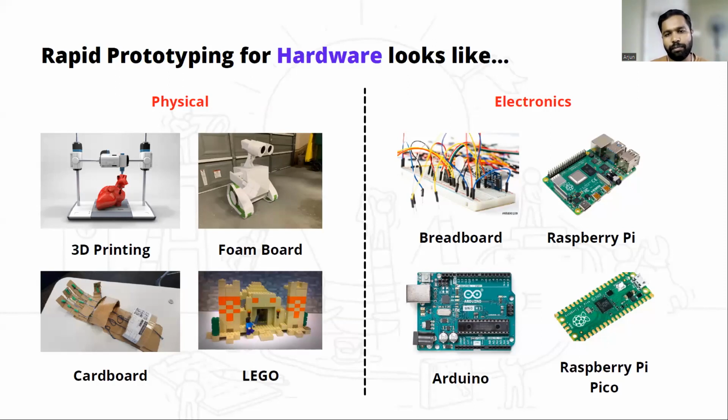So if you go to some plastics manufacturer and say that you want one arm like this, basically they will create the mold, which is the most expensive part of plastic manufacturing. And once they create this mold, they can manufacture thousands or tens of thousands of such arms with that mold. So the initial investment is what is very costly. That is why rapid prototyping helps you reduce all of these costs.